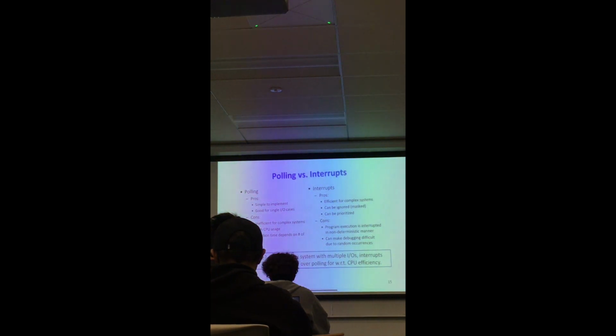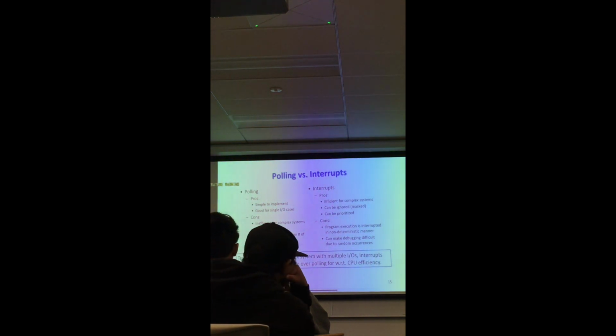Another problem with interrupts is that you lose synchronization. So if you do real-time programming, most likely interrupts will be disallowed in your application because they are unpredictable. In round-robin polling, the cycle time is predictable. You can predict how much time it takes for you to ask devices for attention.